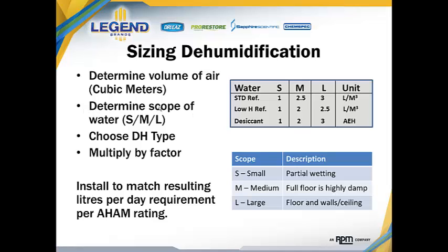In other words, are you dealing with materials that let go of water rapidly, high evaporation rates? If you're dealing with really high evaporation from something like textiles on the floor as a flooring material, then we're going to need more humidity control than you would if you were dealing with something like a hardwood floor, which lets go of water more slowly.